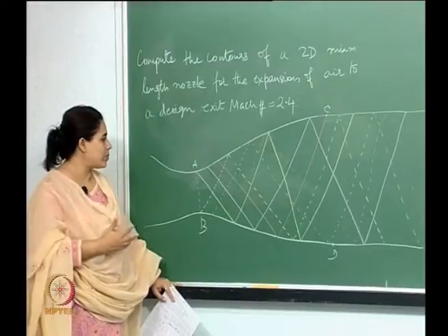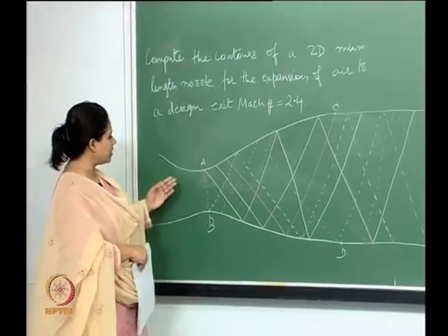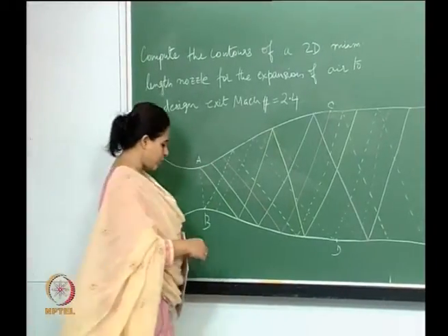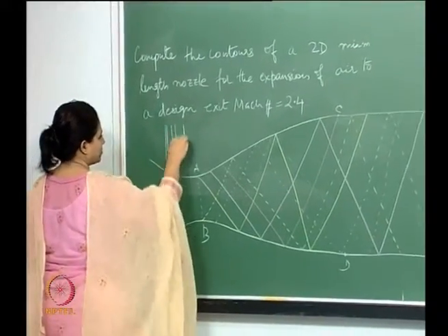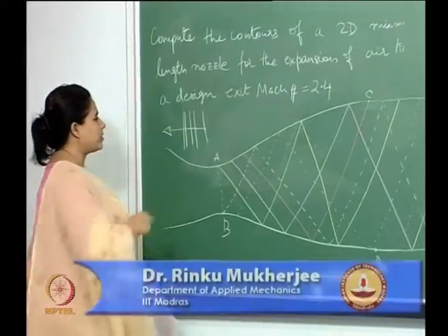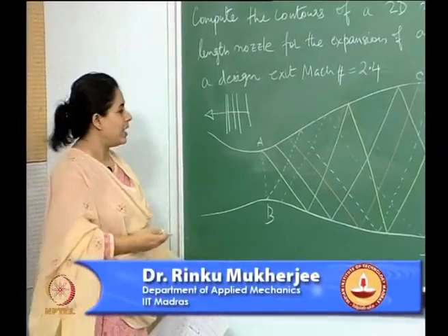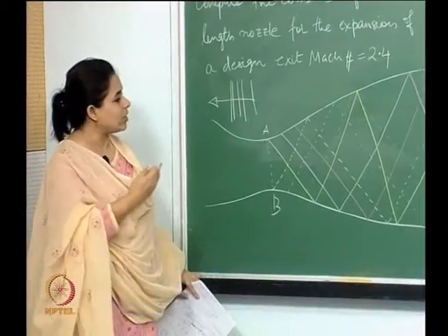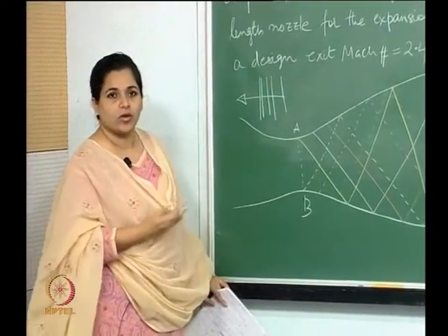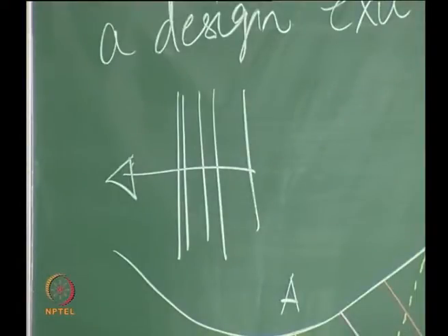Okay. How are we representing this? We are representing this essentially when I have these lines. If you remember the shock tube, right, we represented this as an expansion wave, that the expansion wave, right. That is what we are doing over here as well. These lines essentially mean, so now these are basically characteristic lines or Mach lines, right, with a series of Mach waves traveling.